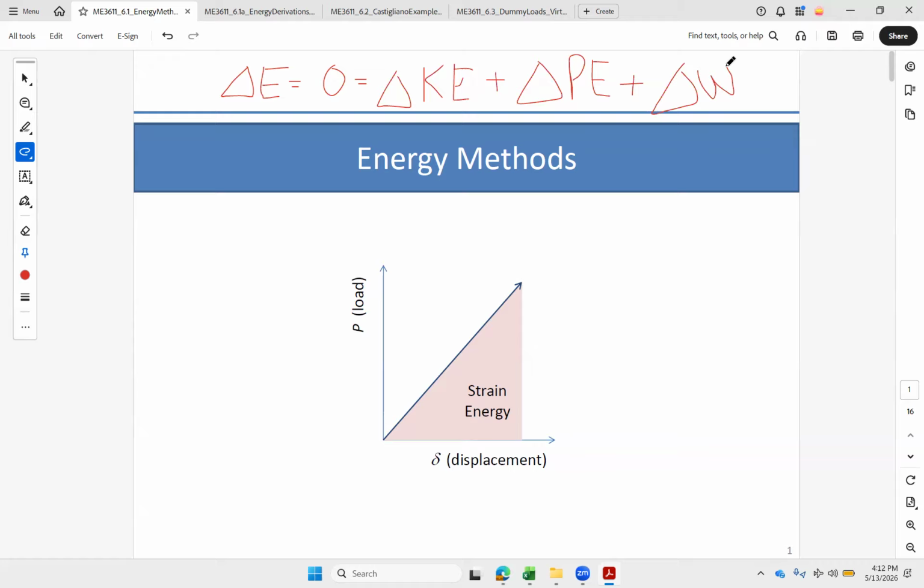Conservation of energy, essentially. Right. And in our solid mechanics models, we have a conservation of energy. We do some work on it via applied and external loads, and that energy is stored in the form of deformation and strain energy like this. So when we think about strain energy in a solid, we apply some load to it and it displaces. And we usually ramp that load.